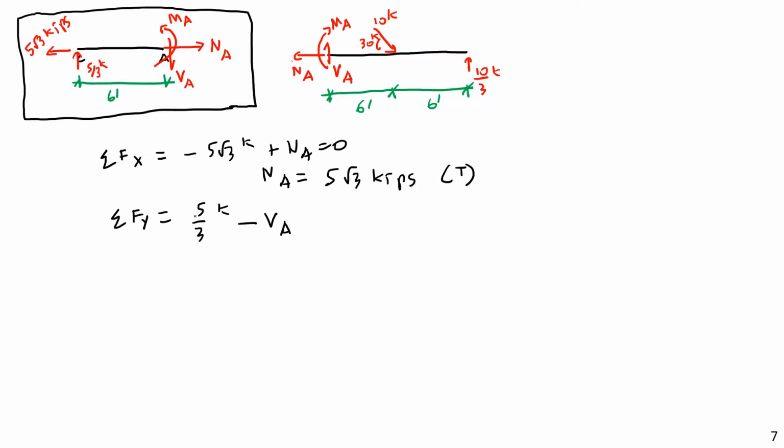So when you're doing equilibrium like this, you can't just say, oh, it's positive shear, therefore put a plus VA in here. No, unfortunately, it isn't that simple. All that matters is whether an individual arrow is pointing upward or downward. So I would have minus VA.